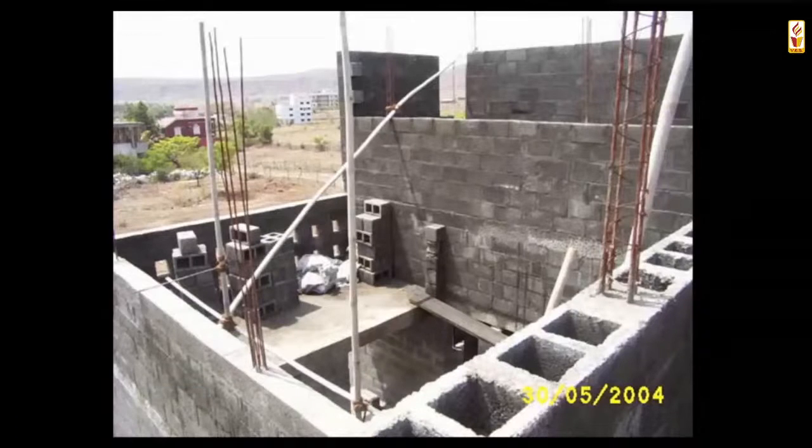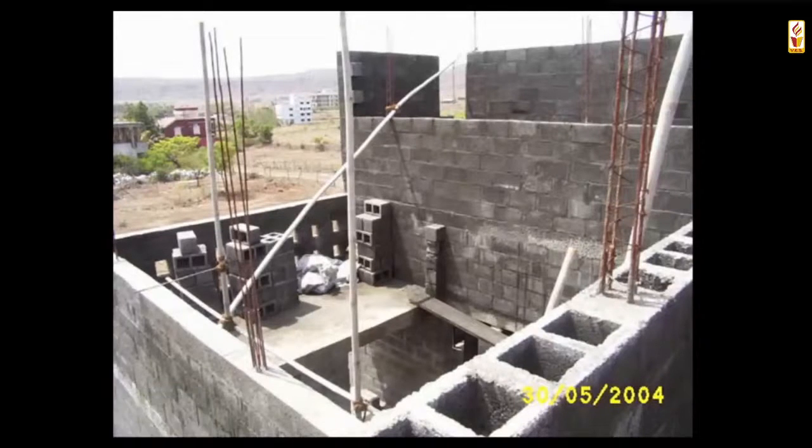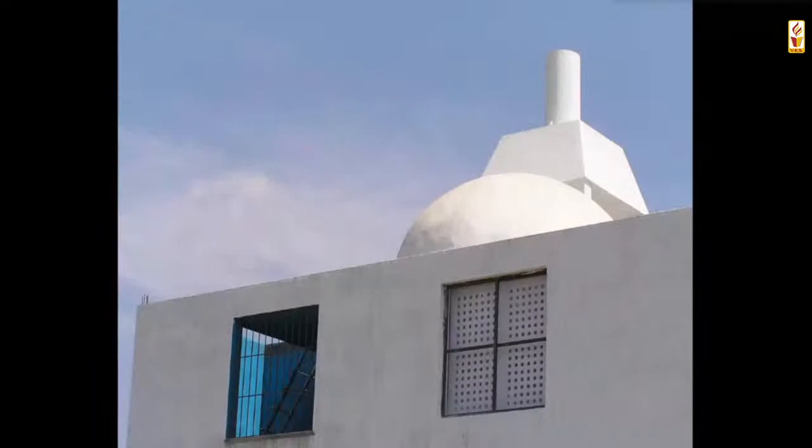And for the last course, generally he preferred that you do concrete of 200, because of the way we do centering here. At that point of time, we never had the steel prop-ups which are now available. They used to hammer nails in the last course, and sometimes you would get hair cracks, but now that's not required. So for the last course we use cavity block and fill it with concrete, so it becomes stronger, and then we do the slab on top of it.